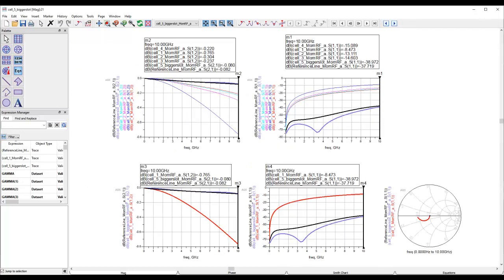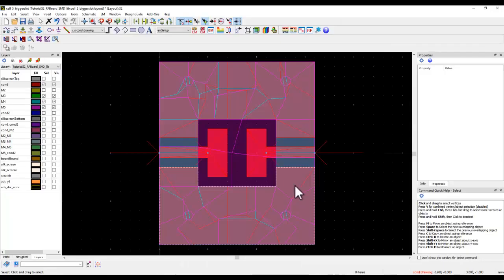Now this particular design I can take and employ in my bigger board, because there's no point analyzing the whole big complex board. We can just analyze a small section, optimize the performance, and this can set a good guideline for my PCB or board designer, and an RF microwave or digital engineer can give this guideline over to the layout person to produce a layout with this particular constraint.